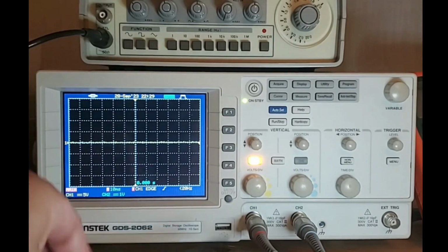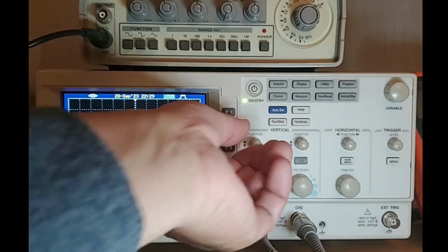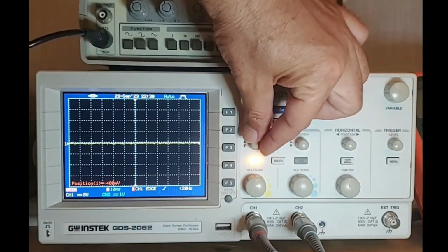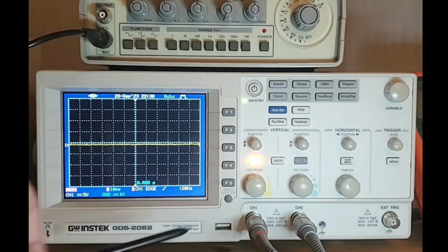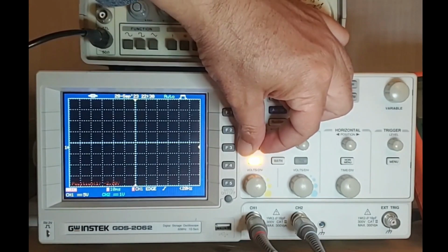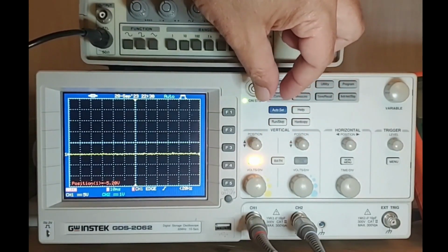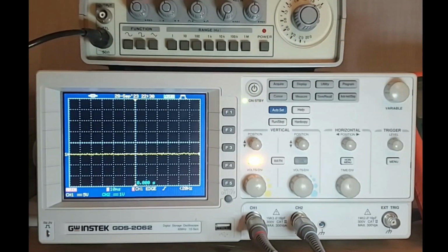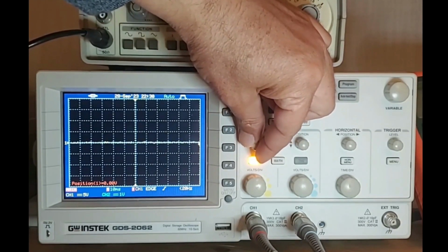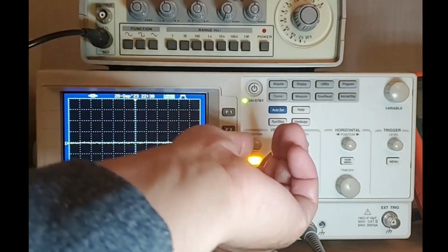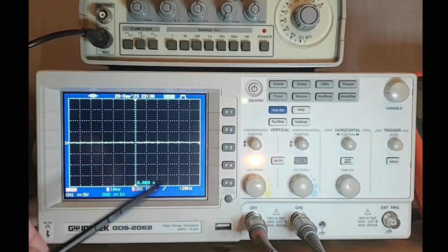Now, channel 1 is represented by yellow color, as you can see over here. I can move the position of this curve up and down using this vertical position knob. It is sometimes useful, because if I want to see 2 different waveforms and I want to separate them from each other, then I can move them up and down. So this is the vertical position, which is useful. You can move your waveform to any position you want. Typically, I would keep it in the center.